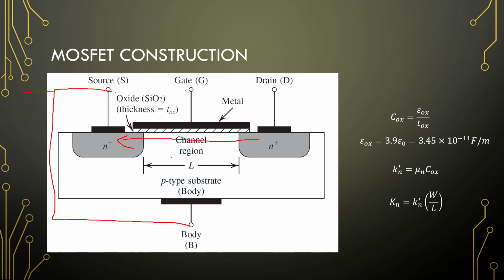Okay, and for that we need to cross a certain threshold voltage that will be called VT in the coming pages. So a threshold needs to be crossed, then current can start to flow, and at first this will be very ohmic, this region, and then it will start to flow very freely as the gate source voltage increases.